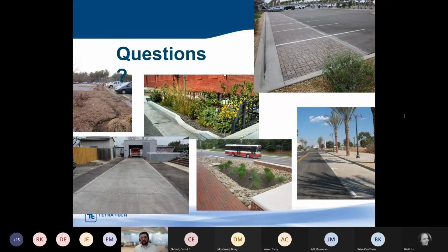For a bioretention area next to a road that's lined in concrete, you probably aren't going to have to replace the concrete. We generally assume you're going to have to replace everything down to the underdrain. Underdrains are usually PVC that should hold up longer, but everything down to the gravel, the media, the vegetation, some of the inlet energy dissipation, all that's going to have to be replaced in 20 to 25 years. But there's a lot we can do to keep them functioning.